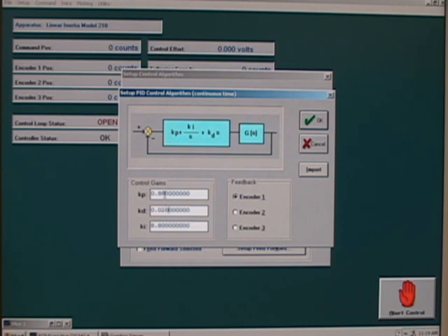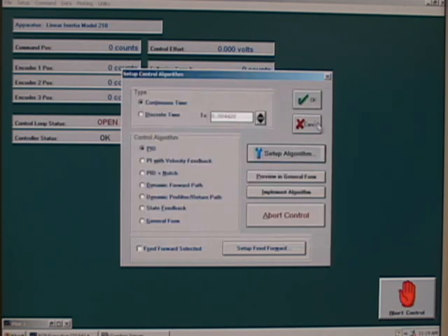Our position gain, which we should have recorded, should be 0.28 times 40, which obviously I haven't done those numbers right now, but I could do that. So let me now just put in some numbers that I have worked with in the past. Let me just say that that's 0.022 for the derivative gain. Make sure you put these in the appropriate locations. The proportional gain, I'm going to say, is 0.88, and the integral gain is 8.8. Make sure you put the P, the I, and the D in the appropriate locations.